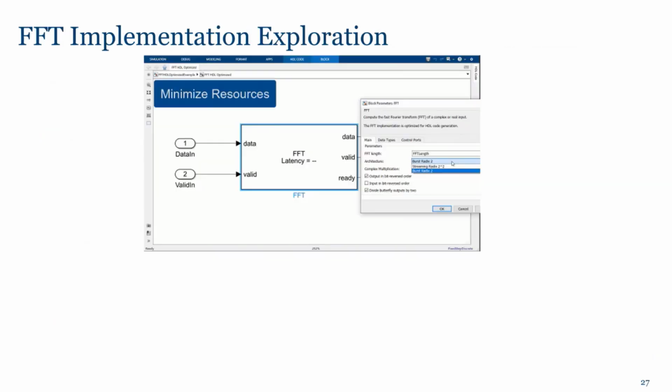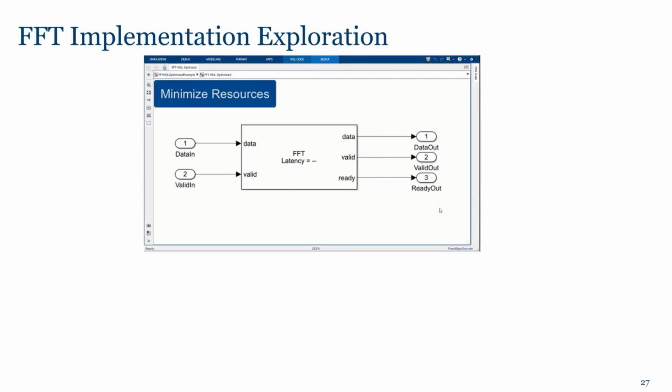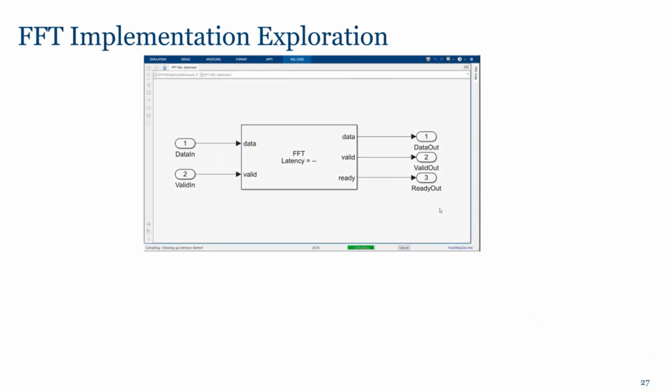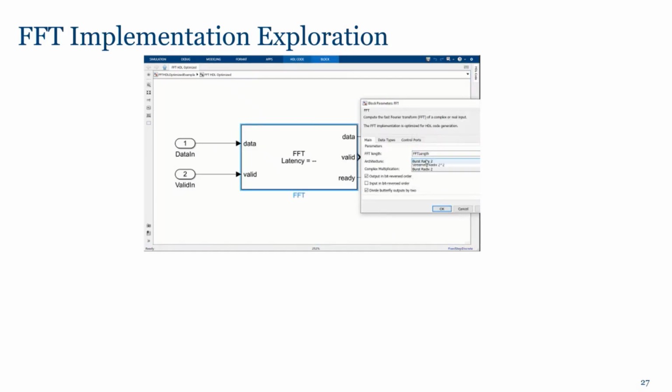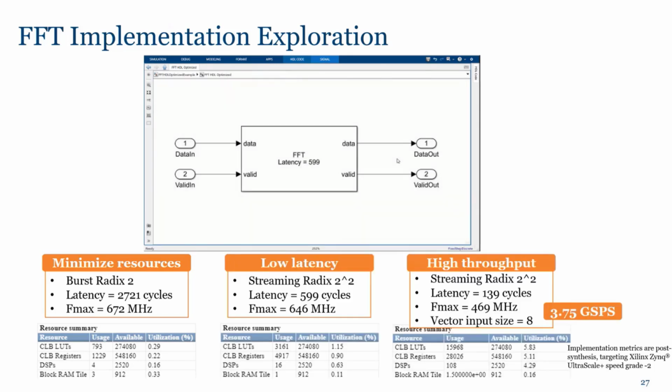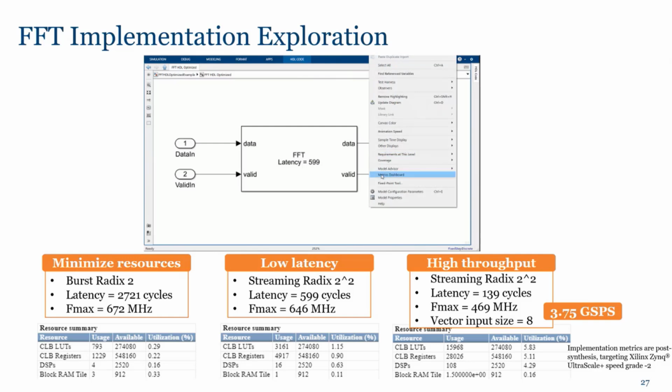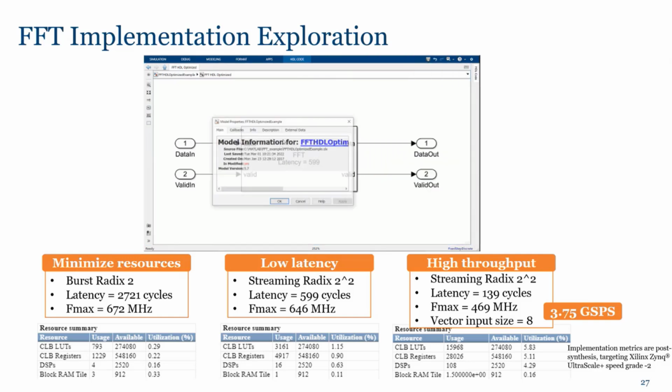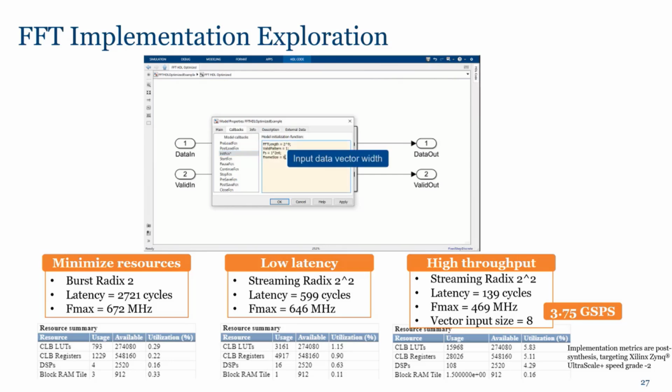So I will dive a little bit into the FFT because there's a very high demand for this type of block. If we go and see here in this short video, you have the FFT, the same block, but you can choose between two types of architecture. And later on, you can choose the architecture or even the vector input size, depending on your constraints and on your requirements also.